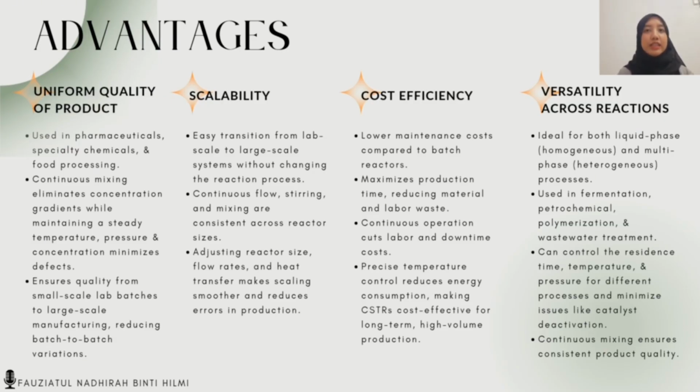Secondly, the scalability. This is because of the easy transition from lab scale to large scale systems without changing the reaction process. The continuous flow, stirring, and mixing are consistent across reactor sizes. Hence, adjusting the reactor size, flow rate, and heat transfer makes the scaling smoother and can reduce errors in production.